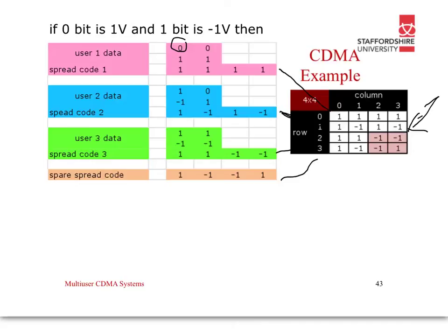Because we're using 1s and -1s, we can just simply do a modulo 2 multiplication. If we kept it in terms of 0s and 1s, then we would just do an exclusive OR operation. And I've shown why we use 1s and 0s, because the shift registers use 1s and 0s.